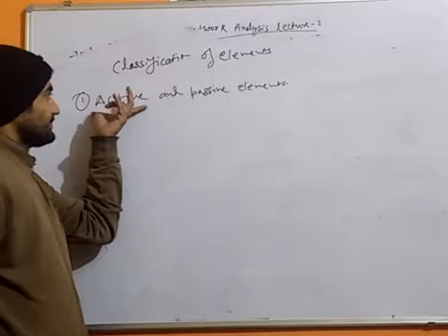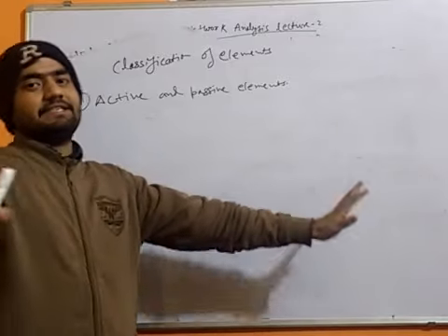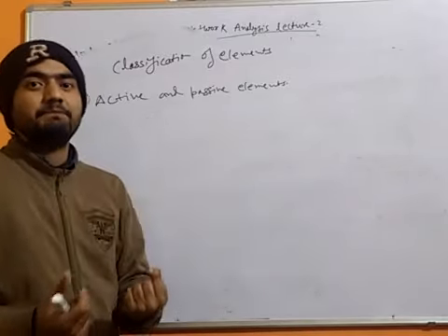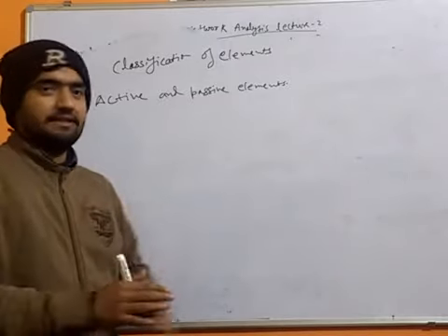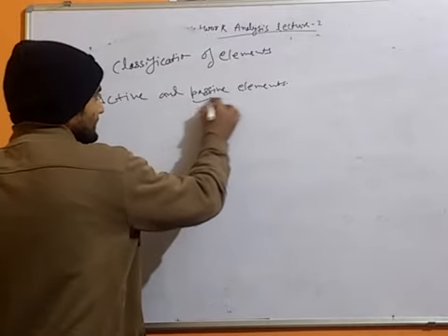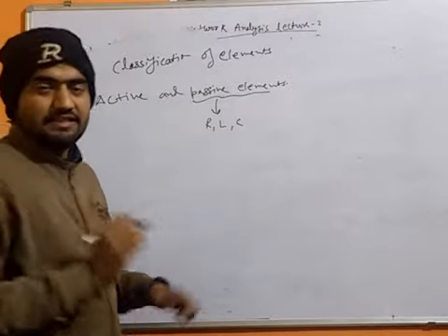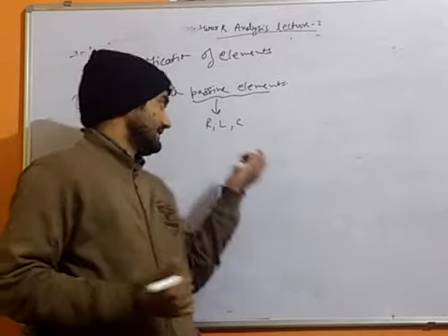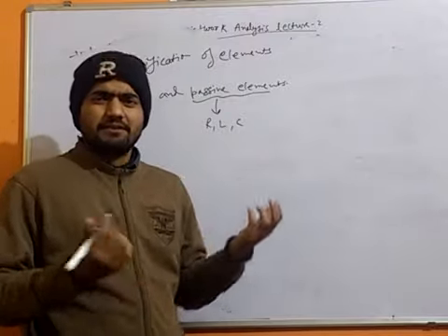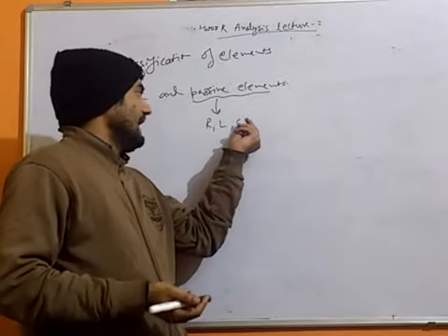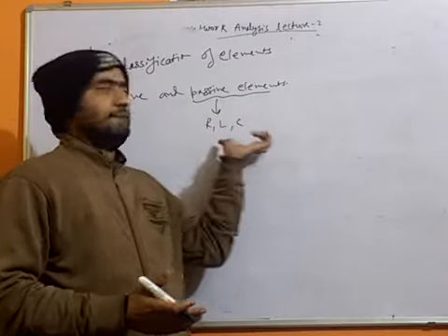Now a passive element is, of course, one that is not generating any power; instead it is absorbing power, or it can store power as well, but not generating power simply. So in the passive class we have resistance, inductance and capacitance. Resistance, of course, absorbs power, and inductance stores power, though somehow it loses something as well, and capacitance again stores power and there is some loss. Overall these are the passive elements.